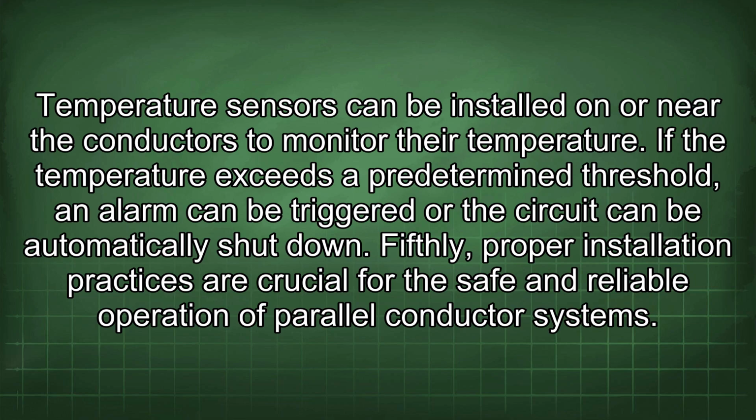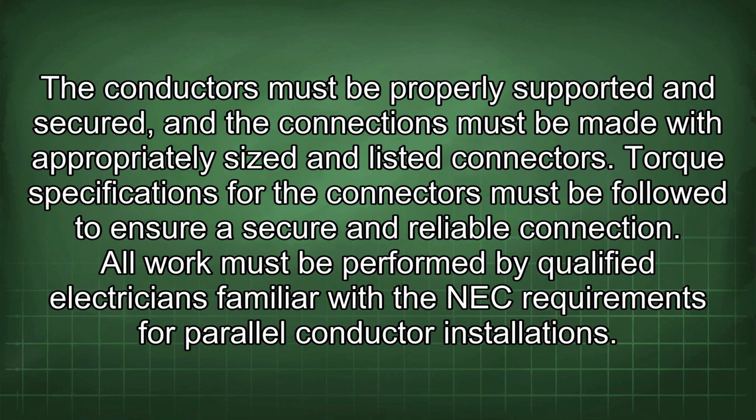Fifthly, proper installation practices are crucial for the safe and reliable operation of parallel conductor systems. The conductors must be properly supported and secured, and the connections must be made with appropriately sized and listed connectors. Torque specifications for the connectors must be followed to ensure a secure and reliable connection. All work must be performed by qualified electricians familiar with the NEC requirements for parallel conductor installations.